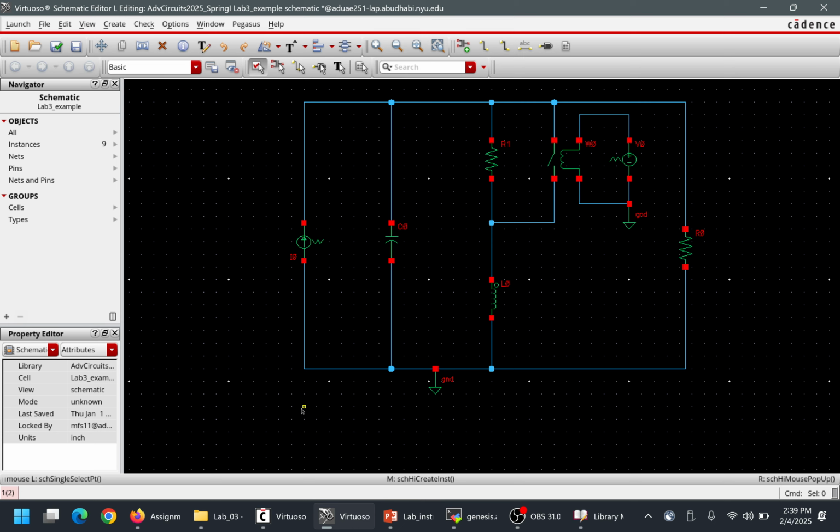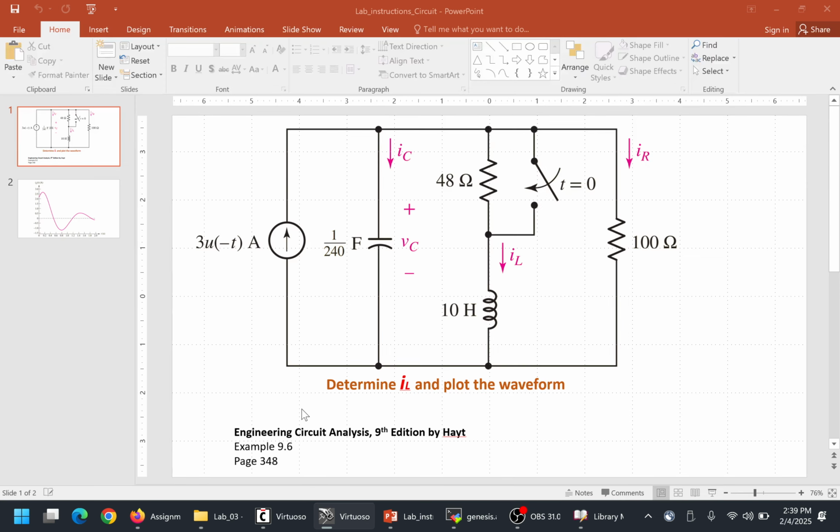Quick question: why do you put a voltage source near the switch? Because in the circuit diagram there isn't a voltage source. No, there is none, but there's a switch, and that switch turns on and off with a specific behavior, so I have to simulate that behavior. I have to come up with an idea for how to do that. This switch, as I said, we assume stays off until 1 second, and at 1 second it turns on. So how can you simulate that?